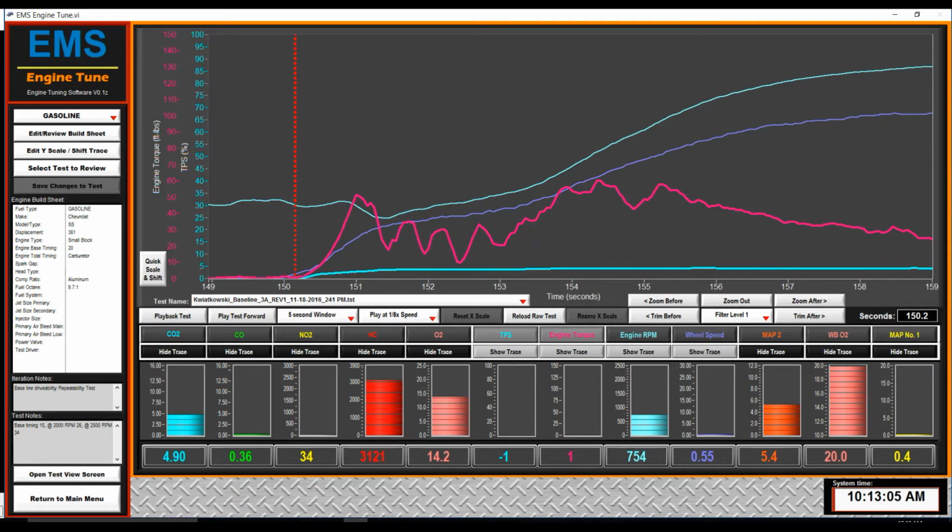To start the diagnostics, we're going to look at the first second of the application of the clutch. So from the 150th to the 151st second, we're looking at the torque that is being generated. Now this torque is measured at the rear wheels, but it is representative of what the engine is putting out. The RPM that we are seeing is engine RPM.